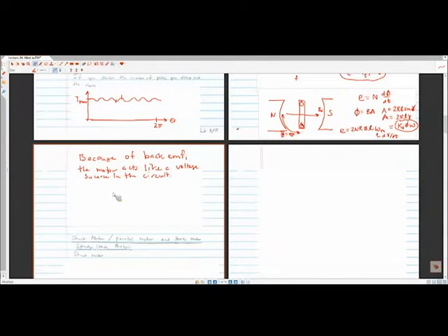If this is a separately actuated circuit, and we'll get into the other ones in a second, that means we have 2 circuits that we can independently drive. So we have terminals for the field circuit. So this is the electromagnet in the stator, right? Which is going to have 2 terminals with it, and we can then drive a flux in this field.